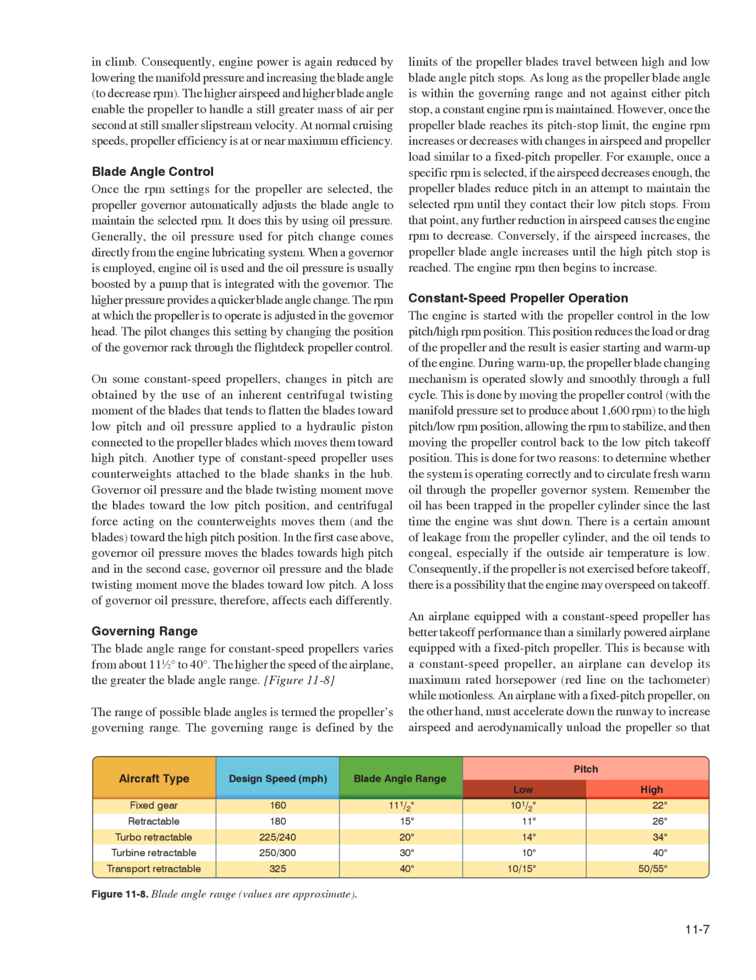There is a certain amount of leakage from the propeller cylinder, and the oil tends to congeal, especially if the outside air temperature is low. Consequently, if the propeller is not exercised before takeoff, there is a possibility that the engine may overspeed on takeoff.